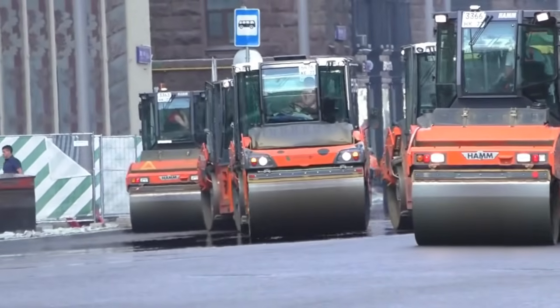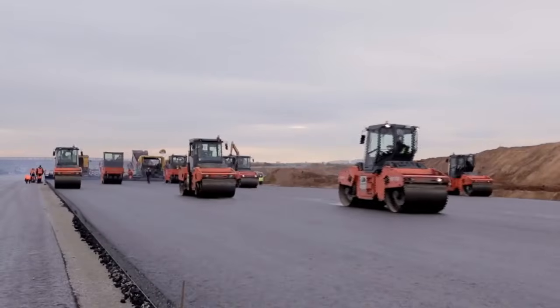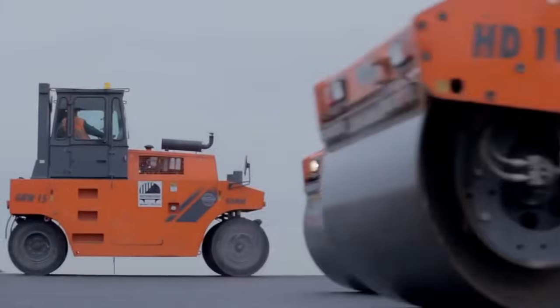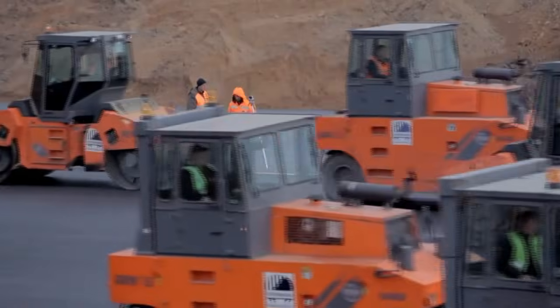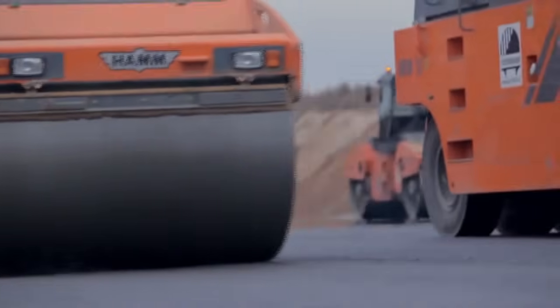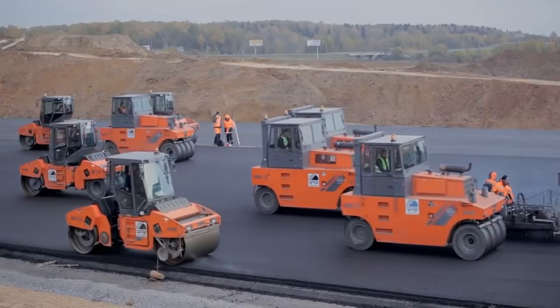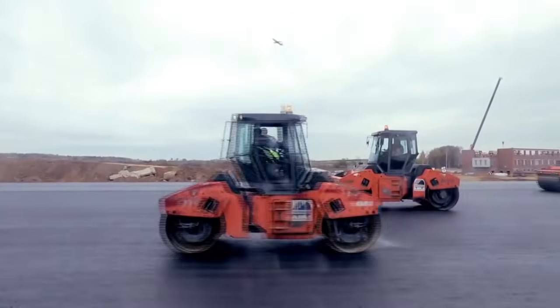After this, the rolling shall commence longitudinally from the lower edge to the upper edge and parallel to the center line of the pavement. Rolling shall be done continuously until all roller marks have been removed from the bituminous surface. During rolling, the wheels of rollers shall be kept moist by sprinkling water from the water storage fitted with the roller, to prevent the mix adhering to the wheels. After final compaction, the tolerance of the surface level shall be less than ±6 mm.